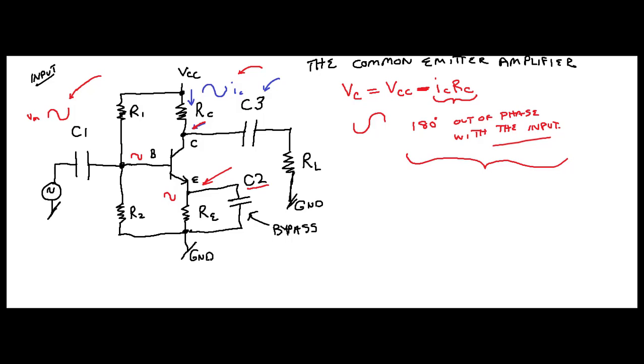And I don't know if I said this to you earlier. This load, this is your output over here, obviously. This amplifier is to power this load, to supply voltage to this load. So that's what it means. And to say that it's common means that both of these are oscillating around ground, which is your common point, because for that signal your emitter passes right through it and is connected to AC ground.